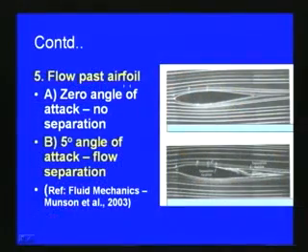This airfoil we can use to see how the separation takes place by placing it at different angles. In this slide you can see the flow past an airfoil. The free stream is coming like this, and here this is the airfoil, and the angle of attack is 0. If the airfoil is perfectly made in such a way that no separation takes place, you can see that the flow is going like this. So, there is no boundary layer separation.